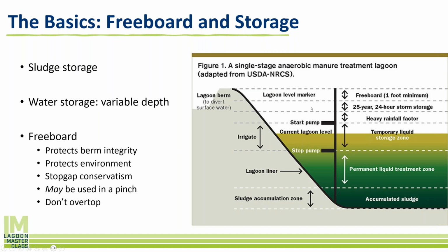That being said, this area right here, we can wait for a rainfall or storm surge. Sometimes operators will use this tactically or strategically, provided that their regulators allow them to do that. Not every state will allow operators to operate within their freeboard. Some do under certain conditions.